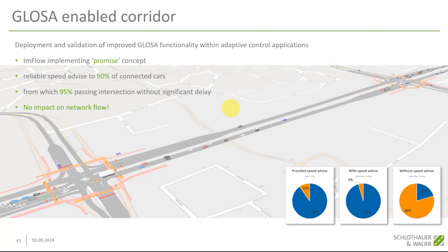The same is true for CCAM integration, CCAM messages, information about individual vehicles coming at certain speeds towards the stop line. Usually when you don't have CCAM, you're having a detector, and as soon as ImFlow is counting a vehicle, it is creating a digital representation of that vehicle, simulating it and tracking its position.